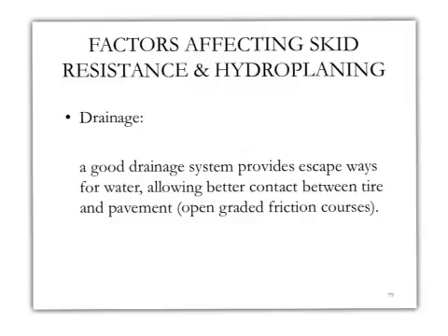One of the solutions to do that is to use what we call open graded friction course materials. In open graded friction course material, we would use finer aggregates as well as very big size aggregates, and there will be one size in the middle open or missing. So we're now increasing the permeability of that layer. Typically it's the top 1 or 2 inches where you let the water go through it, and then we would make sure the water is collected from the 2 sides of the pavement once it infiltrates through the top